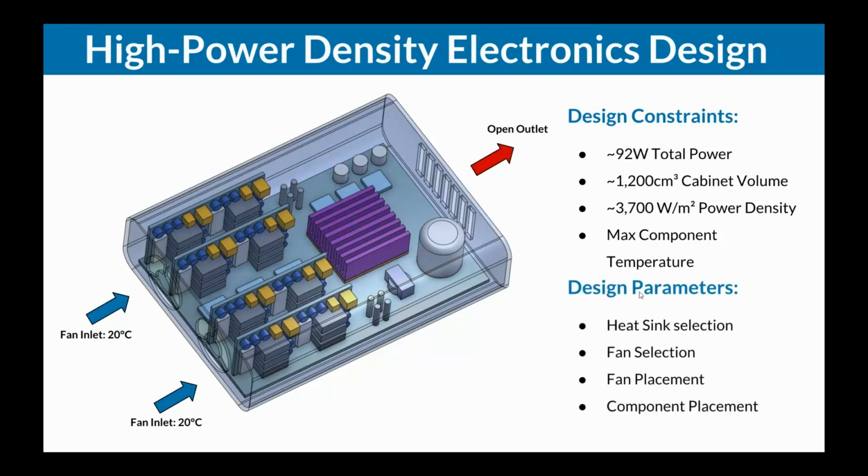And now looking at this, we are asked to validate whether or not the cooling strategy we designed or engineered here is actually sufficient to operate all of these electronic components under a safe temperature, right? Even at peak load, peak load of all of the semiconductors in here. And so typical design parameters we're seeing customers looking at are, first and foremost, heatsink selection here on the CPU, right? It's something that's present very, very often. Also material selection of the heatsink, etc. So that's one thing, and we're going to look at it today.